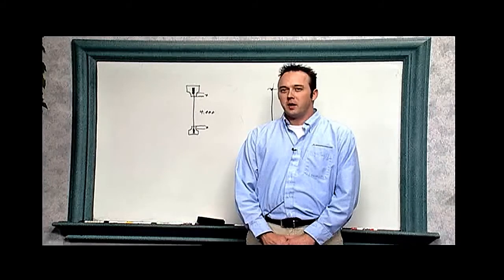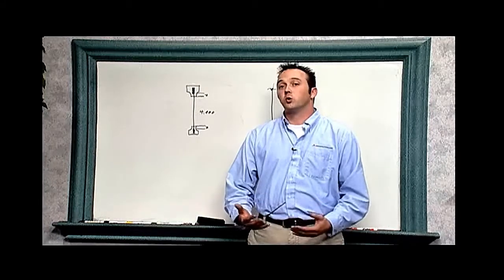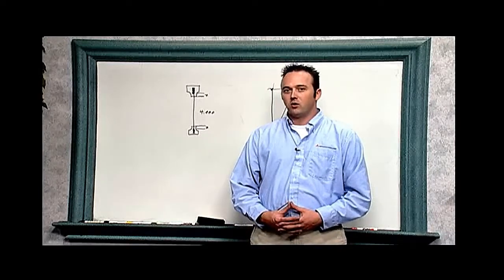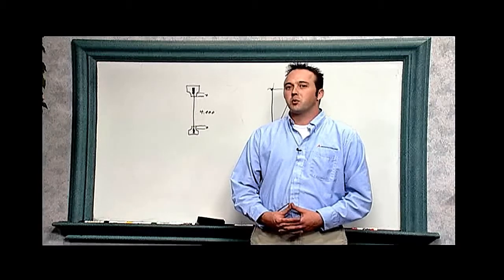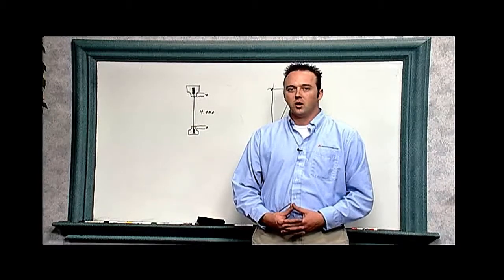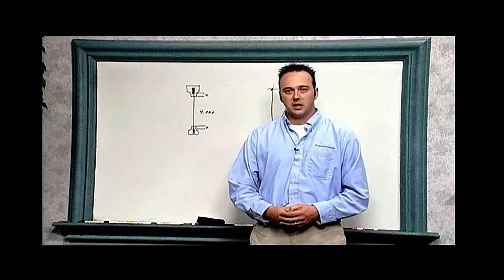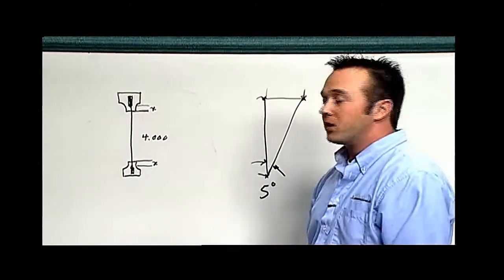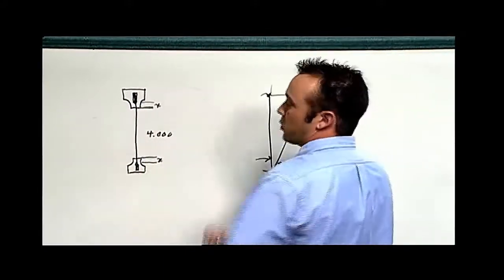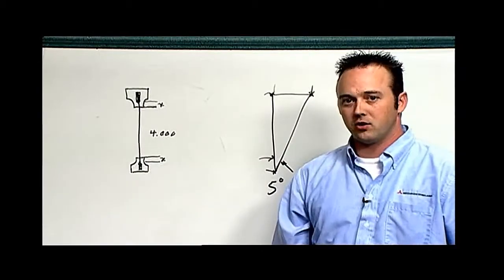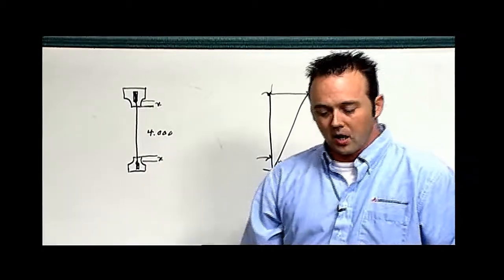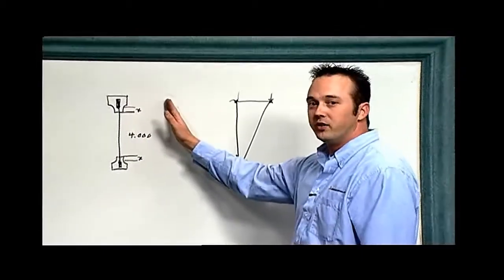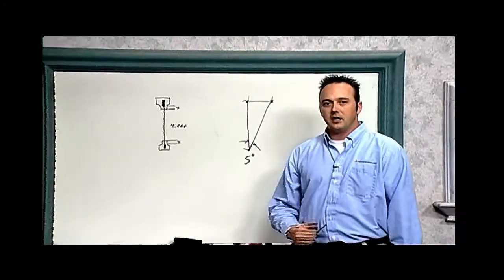A lot of wire EDM applications, when people are doing a lot of form tools or some sort of a cutting tool, instead of cutting with an actual taper angle called up in the program, what they like to do is they pre-tip the wire to a locked position for the entire contour of the shape that they need to cut. So in an application like we have our two upper and lower flush cups, I'm going to need to wind up tipping these things to a pre-tipped angle and locking them in that position for the entire burn that we do. Okay, so what I need to calculate is how much movement is going to be required in that U or V to meet the angle that I need to cut at.